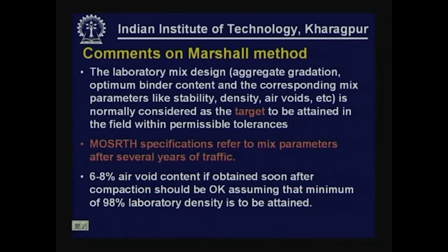The laboratory mix design, that is aggregate gradation, optimum binder content and the corresponding mix parameters like stability, density, air voids, etc., is normally considered as the target to be attained in the field within permissible tolerances. Whatever is established in the laboratory, and you say this is the binder content and these are the corresponding properties that we obtained in the laboratory, these are to serve as target values to be checked for in the field.